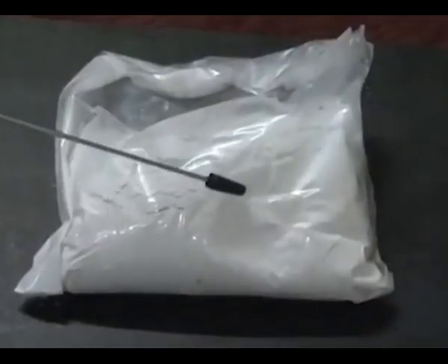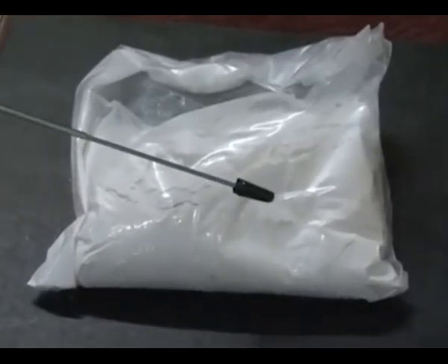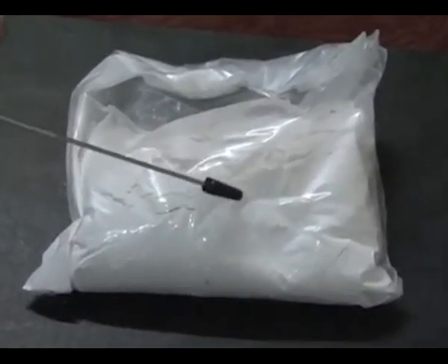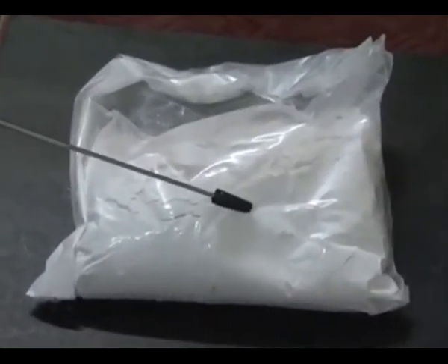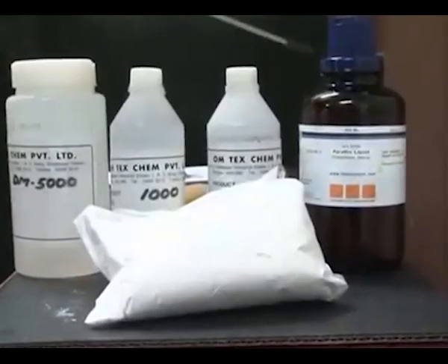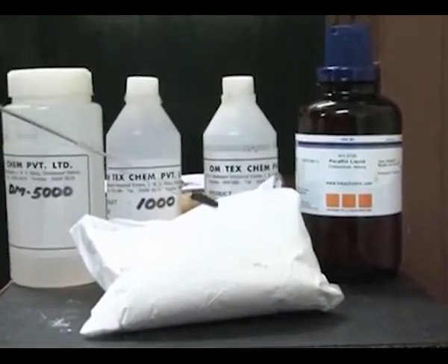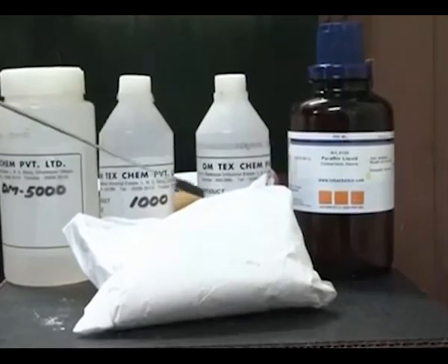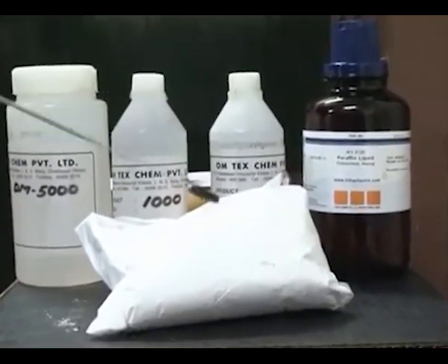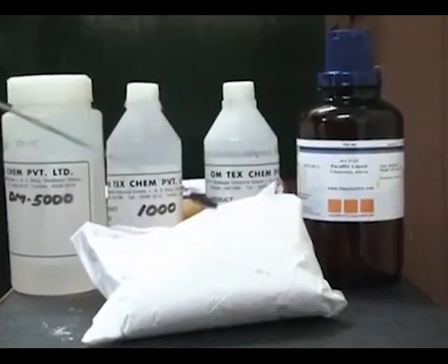The third major element in the medium making is the softeners. In the present condition, we are using the stearates. This will change the viscosity of the polymer medium by assisting the plasticizers. These plasticizers and the softeners combinedly change the medium viscosity and thus decide the flexibility of active abrasive grain in the finishing zone.